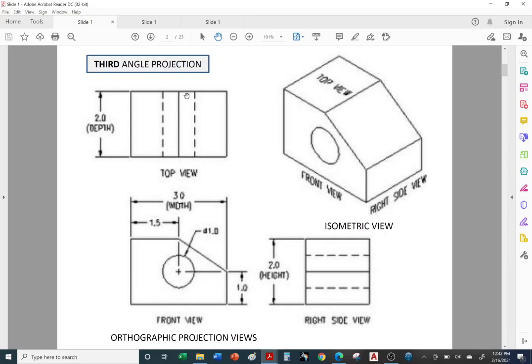They're called hidden lines. And always note that they line up with the quadrants of the circle. Just like on the right side view, I did not mention this earlier, but here we go. We have the dashed lines lining up with the top quadrant of the hole and the bottom quadrant of the hole.